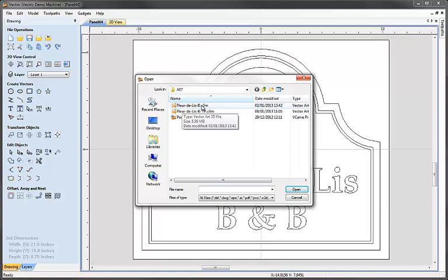I would not be able to import data from that file if I tried to, even though it's able to find it in this open form. I need to make sure I select the one where we've calculated those toolpaths, either in VectorArt 3D Machinist or Cut 3D, and then save the file that contains those toolpaths specifically. So here from the project folder, I'm going to click on fleur-de-lis b-tp, and I'm going to hit the open button.